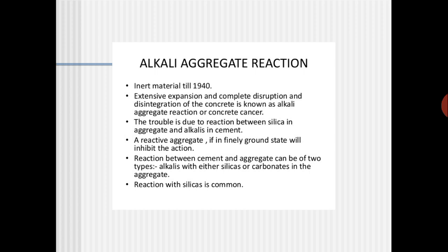Then there will be expansion of the whole concrete. When the expansion increases, the voids increase in between the sand and the aggregate. Then automatically the strength is going to decrease.